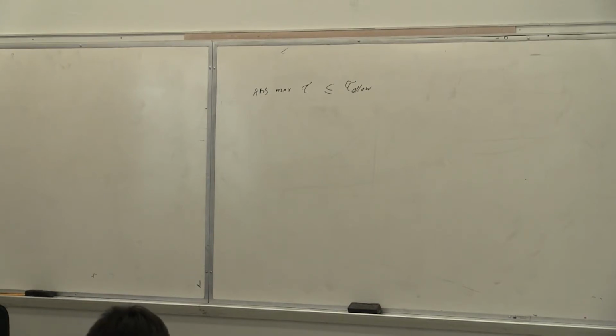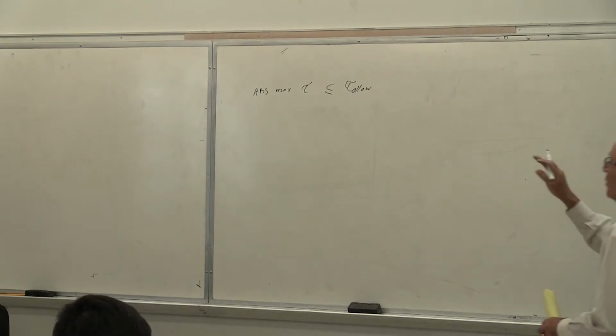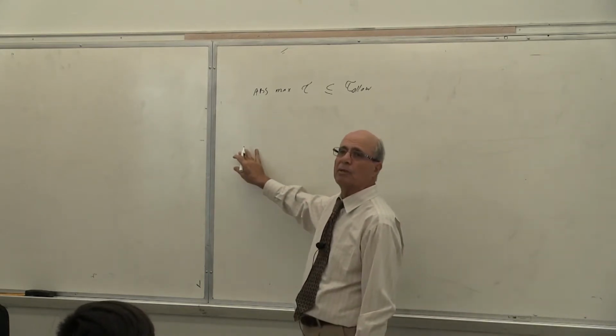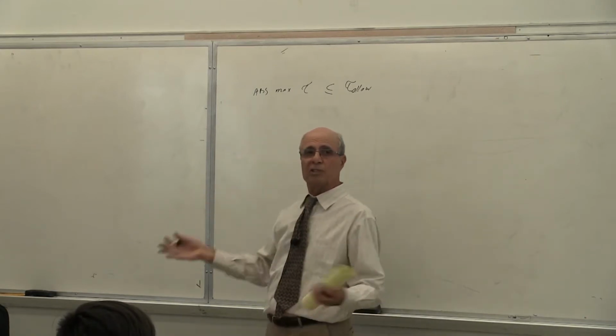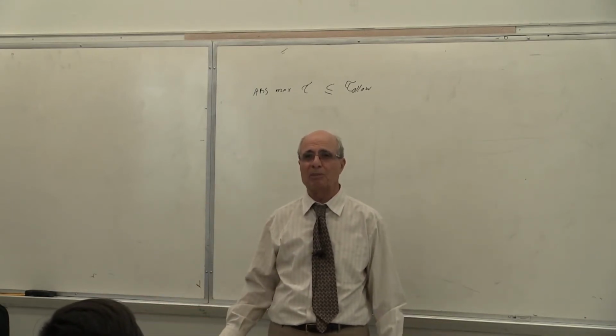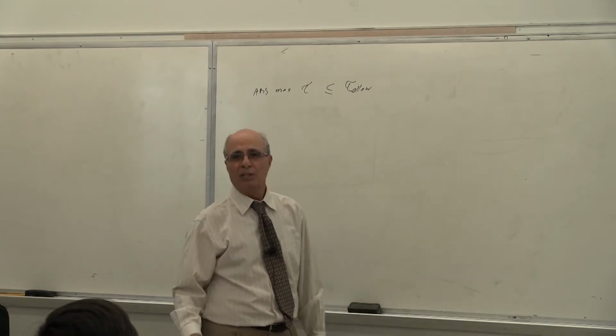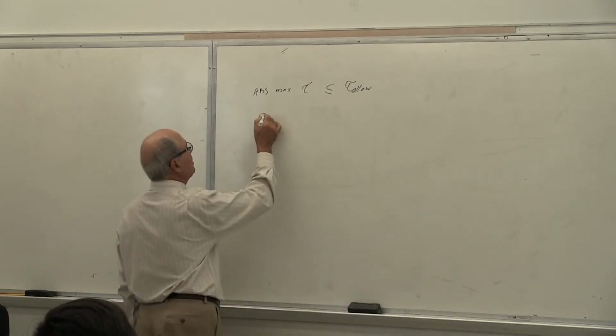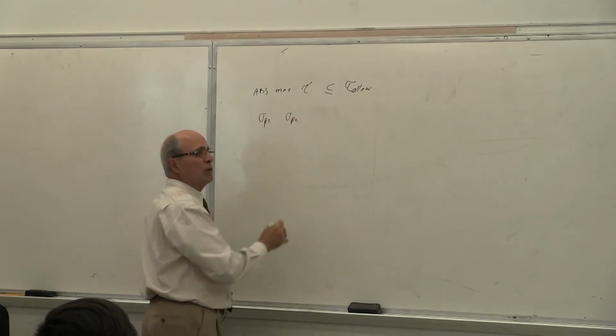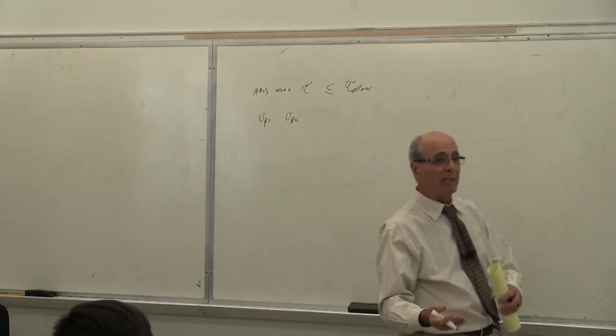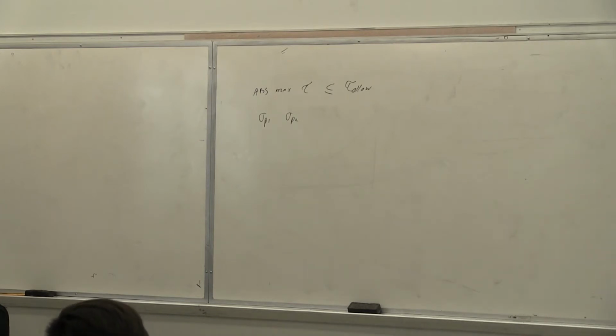However, there is another one, because we have the tau max and we have sigma max, yes or no? Correct? What's the principal stress? Well, you are calculating the principal stress. Principal stress gives you sigma max, 2 principals, sigma principal 1 and sigma principal 2. In ME 218, somebody said we call it maximum minimum. Here you can call it A, B, or whatever. But one is larger than the other one in magnitude, yes or no? And that one also should be less than sigma allowable, yes or no? Because otherwise my system is not safe. But these are 2 different criteria.